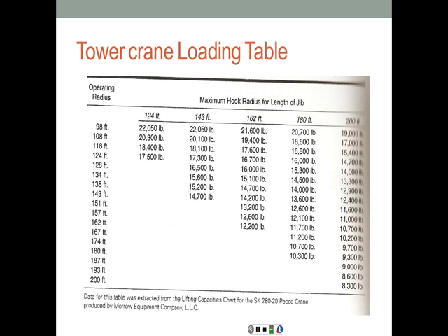And that's basically it for cranes. As you can see, the crane problems are going to be very simple. It's going to be related to selecting the proper type of boom or jib length, knowing the operating radius and knowing the load, or based on a given length of a jib and based on a given operating radius, we're going to have to determine what is the maximum load that can be carried at that specified radius.